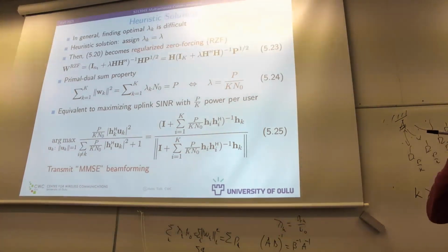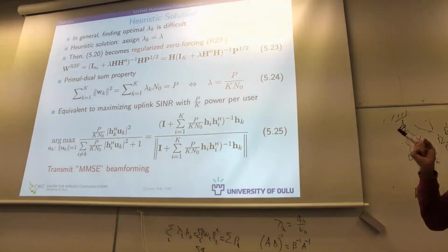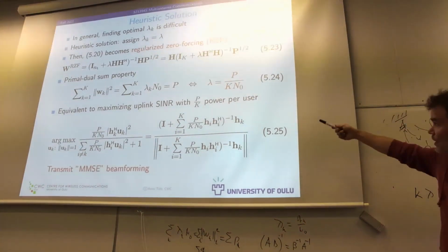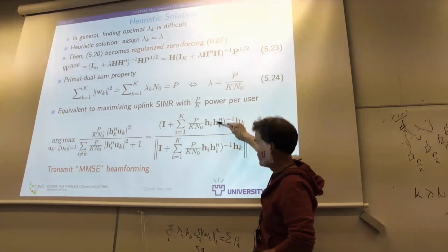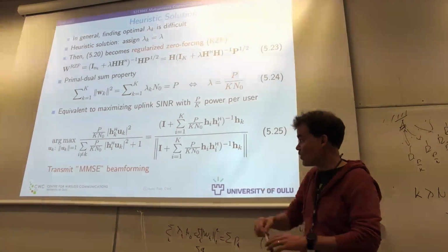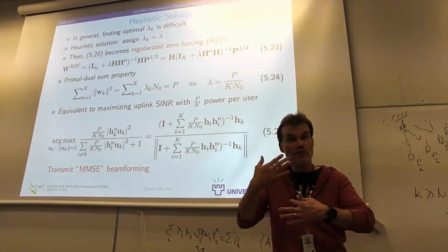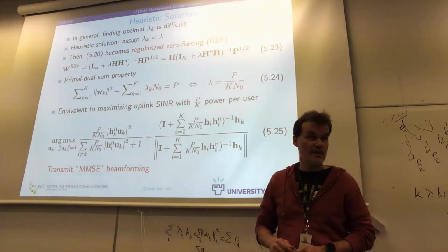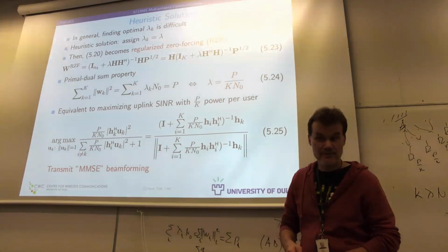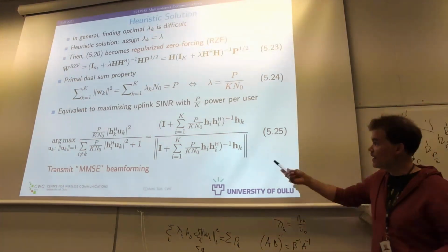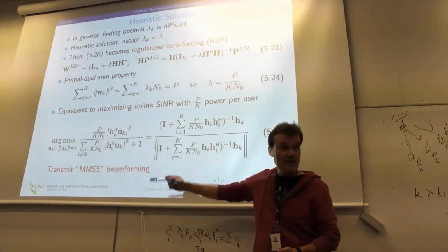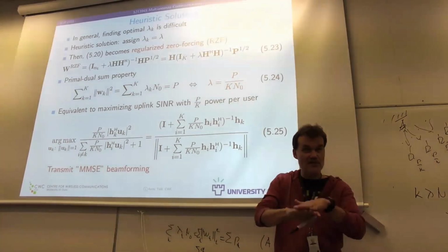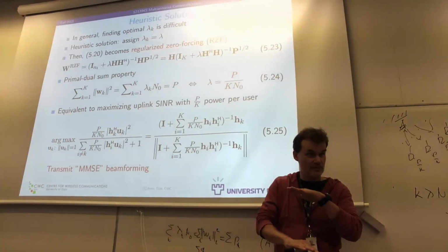But for this, if we have a fixed power budget, right? Then we can compute for that given fixed power budget P this transmit MMSE beamforming. These are the normalized beams now, and then we can do power loading for whatever objective. So it's for max min, the max min SINR, right? Well, you can pick any arbitrary value of P here, and then also compute the minimum power solution using these beamformers. Of course, beamformers are not matched with the resulting power, right?